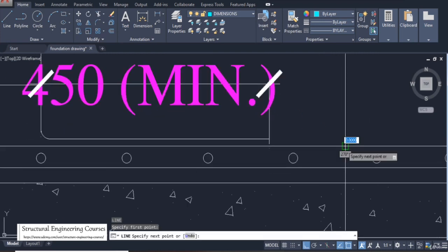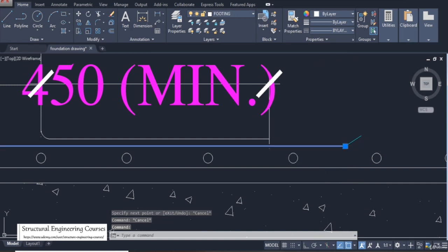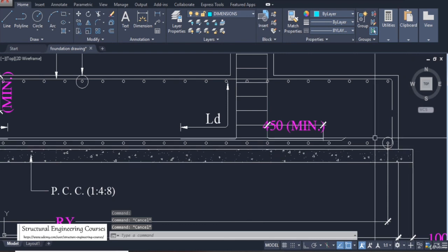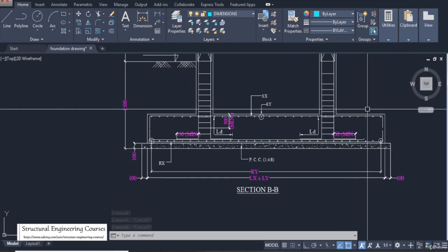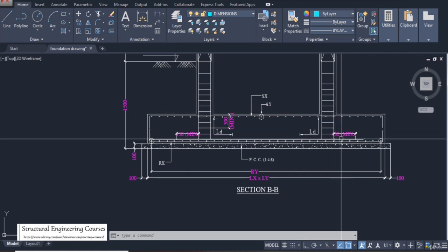What basically we are doing here is putting the reinforcement as per the design requirements only. We don't need to provide an all-through bar here. As the shear requirements only act at a distance of d, we can just provide extra bars at a distance of 900 mm only.